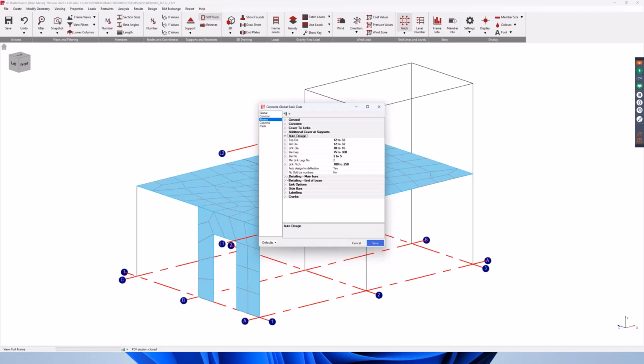For the curtailment, the program uses several detailed rules and settings. The most important setting is the beam curtailment style under the detailing main bars. So the beam reinforcement can be detailed in one zone, same reinforcement all along the beams, no curtailment, 2 zones, left and right zone reinforcement, or 3 zones, left and right zones, and the middle zone reinforcement.